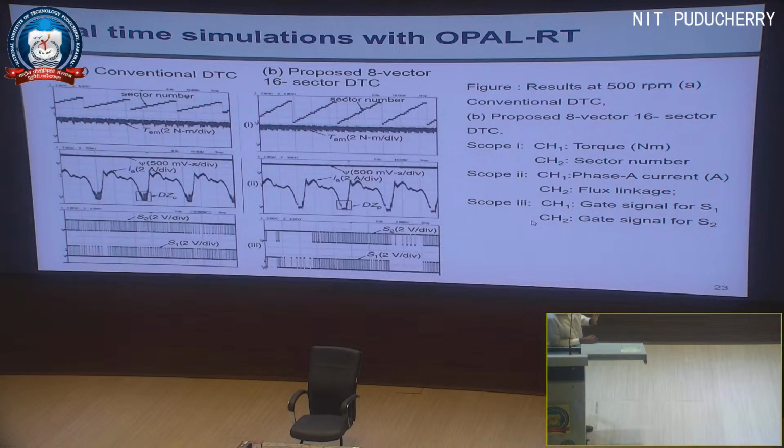As I said, later on we also found one of the major disadvantages with our approach: even though we could reduce the negative torque as well as the current during the zero torque, we were not able to increase the speed beyond a certain value. Even though our motor is rated for 3000 rpm, beyond 750 rpm our results are showing differently. So we have to stop at that point, but it is anyhow a starting point to address the torque ripple, which is the major problem, the hurdle in using the SRM in the electric vehicle, right?